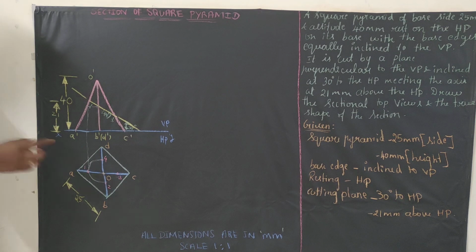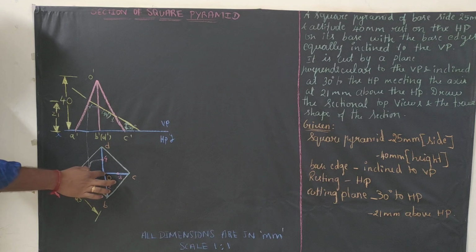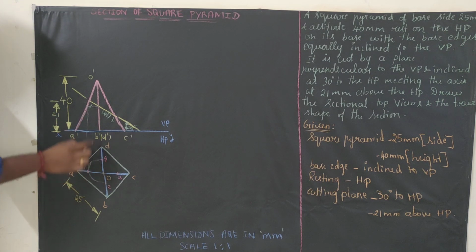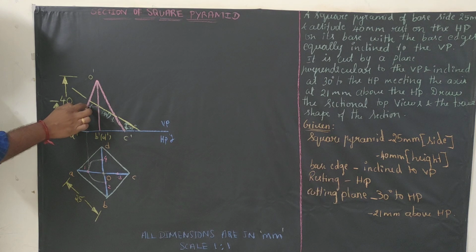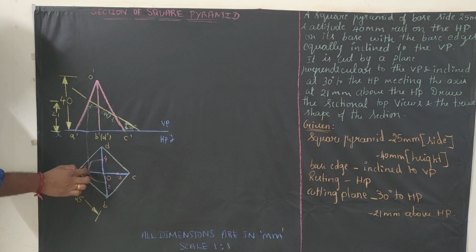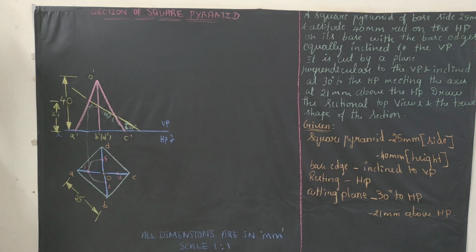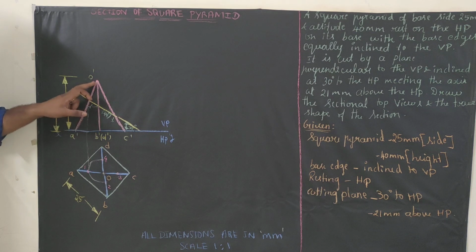After that, what you need to do? Take your compass, measure from here to where you got this. That is the point which you vertically dropped, right? From here you draw a horizontal line. From here you draw a vertical line. It will be meeting OA at one point. From here to that point, measure and try to cut an arc above and cut an arc below like this, with the white chalk, so that you can get 2. That is, 2 dash is between O dash and B dash. So here you will be getting 2. 4 dash is between O dash and D dash.